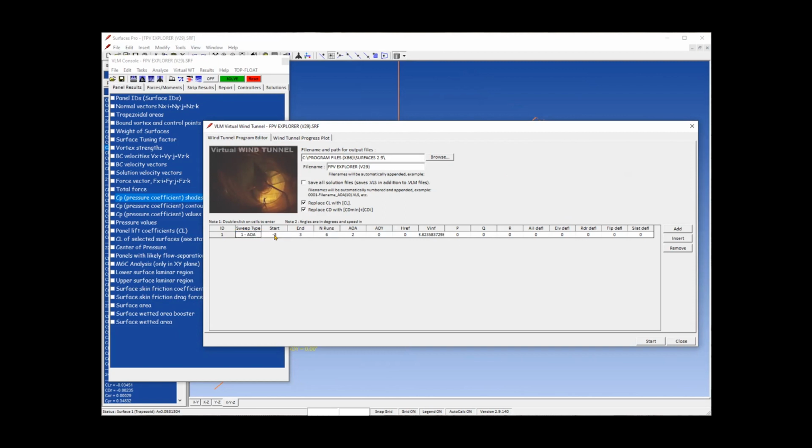Double-click the Sweep Type cell to open a list of sweep types. Here we are going to perform an alpha sweep. Double-click on the Start and End cells to set the initial and final values for the sweep. Start at -5 degrees, end at 5 degrees. The difference between the two is 10 degrees. Therefore, using 11 runs ensures a list of -5, -4, -3, etc. degrees, rather than having some results fall between integer degrees. This is not a requirement, but makes it easier to interpret results.